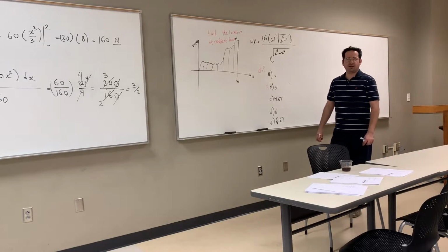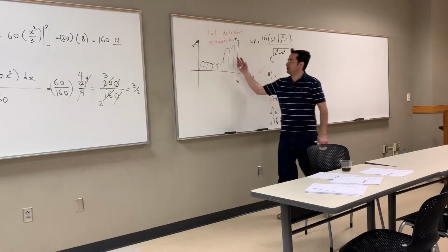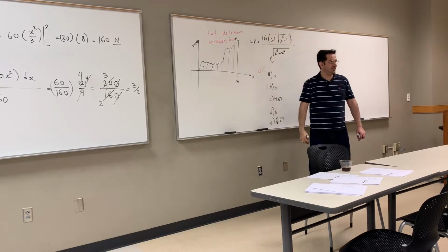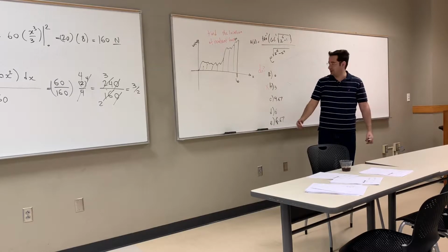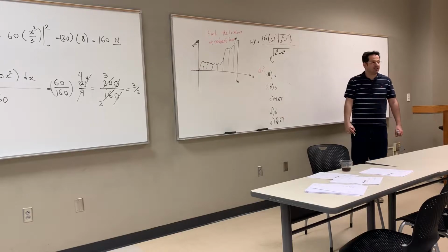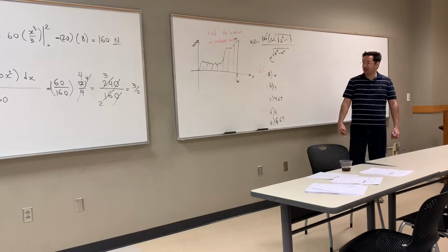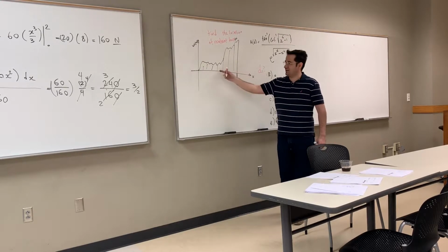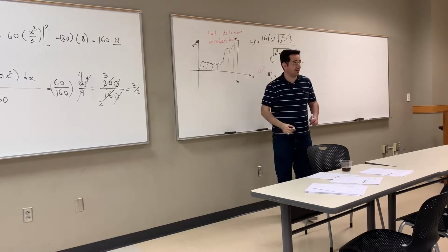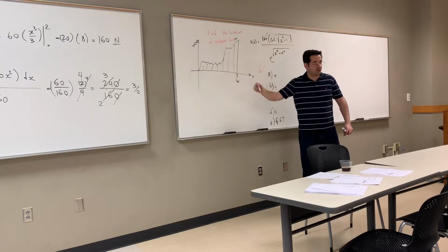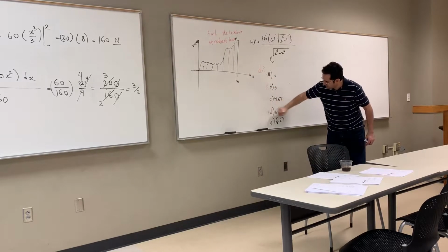So you go to the next possibility. It's not going to be at 0 because you have some load here, right? If you didn't have any force, it would probably be 0. But you can reject this. Now here come the three options. It will not be at 6, for the same reason: if you had a point force at 6, yes, the line of action would be at 6. But it's not a point force, it's distributed, so you can eliminate this.